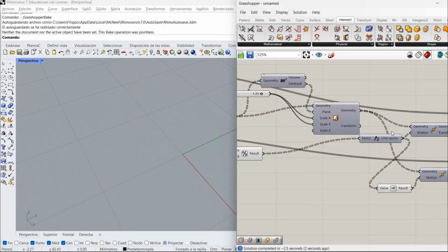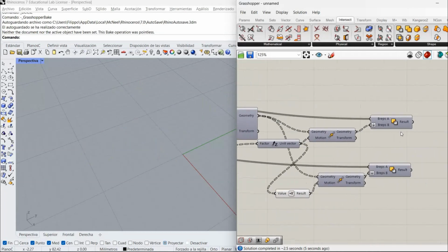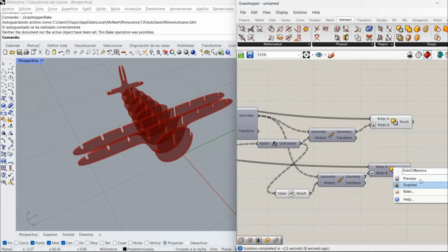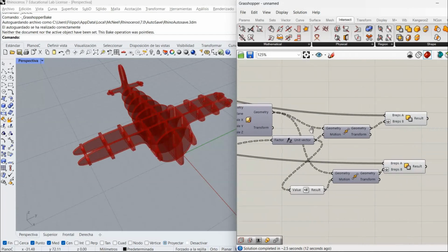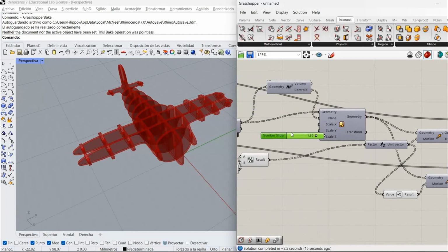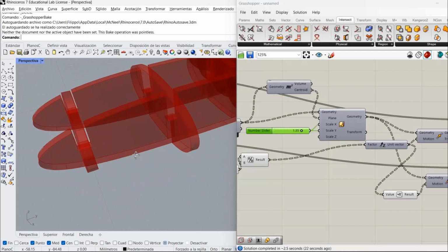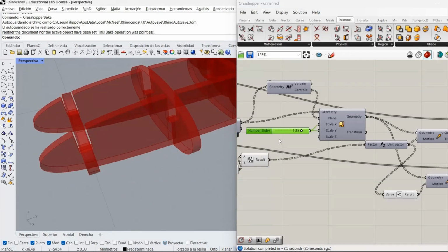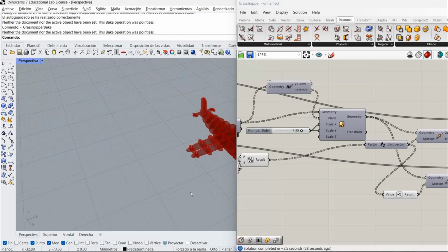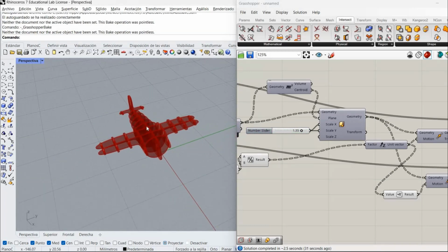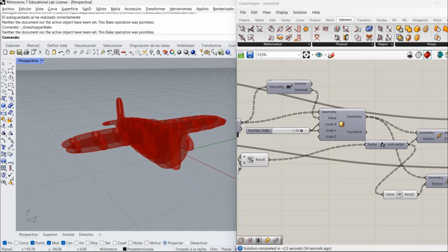I'm going to turn this off, and I'm going to turn this back on. Okay, now it's a number above 1, so we are making them bigger, and we can see that those fixings are a bit loose. Okay, so depending on, as I said, the laser cutter that we're using, the power and all of that, we might have to adjust this however we want. We might want it to be very tight. We might want it to be a bit loose.